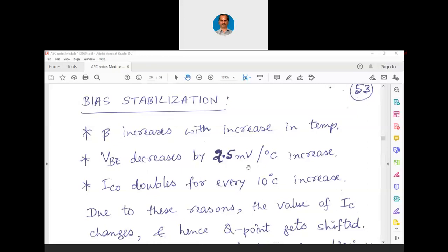Because resistor follows Ohm's law. Even capacitor and inductor, they also can follow Ohm's law. For example, XC is 1 over 2 pi FC. XL is 2 pi FL. Which we can say that to some extent reactance is following Ohm's law, because reactance is nothing but the AC counterpart of resistance. So that way resistance, capacitance and inductance are classified as passive devices because we can predict their behavior for a given DC or AC condition. But we cannot predict the behavior of diode and transistor so easily because they are non-linear devices.